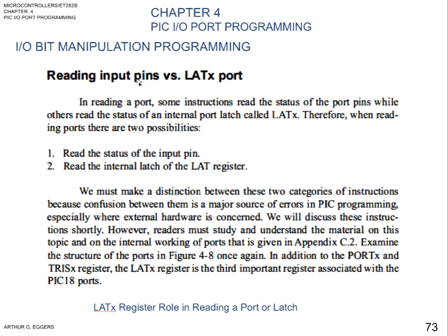Reading input pins versus a latch at a port. In reading a port, some instructions read the status of the port pins while others read the status of an internal port latch. Remember, latches set and they don't change unless something else causes them to change their levels.